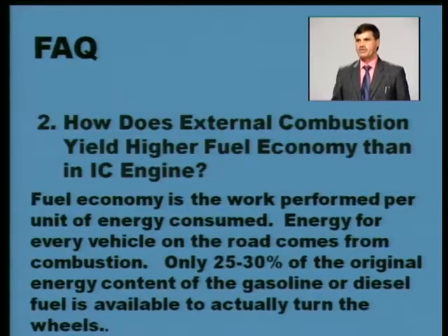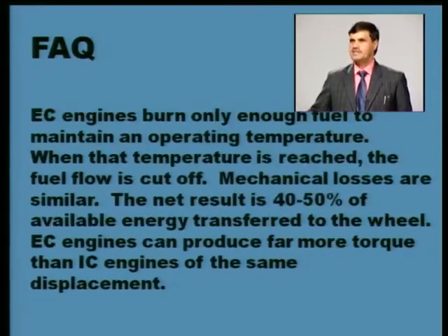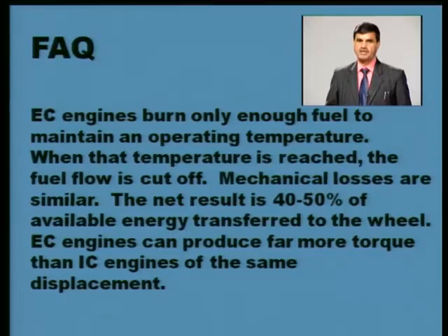From the fuel economy point of view, we have compared that in most cases the efficiency of the internal combustion engine is higher, but as I said, in some special cases the thermal efficiency of an external combustion engine can reach between 40 to 50%. So significantly higher efficiency can be obtained in recent external combustion engines also.